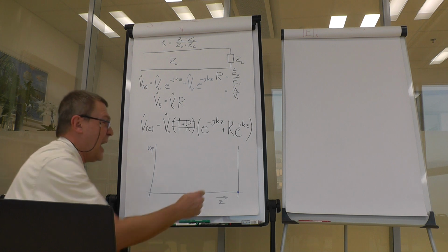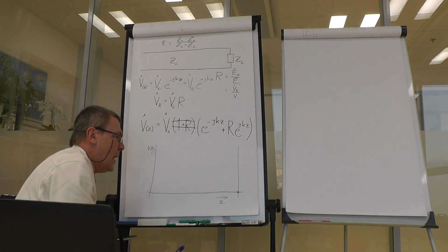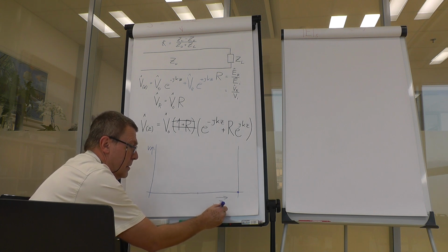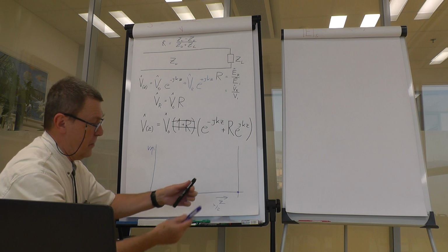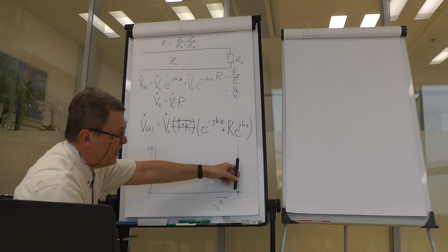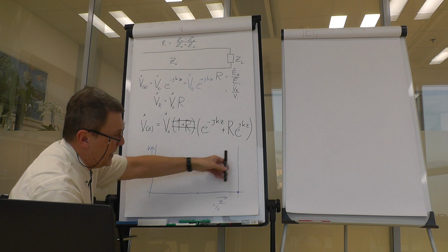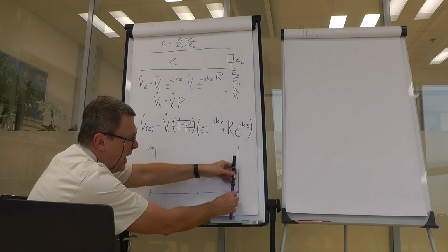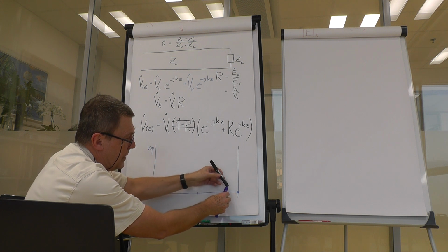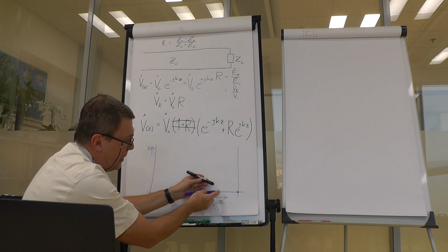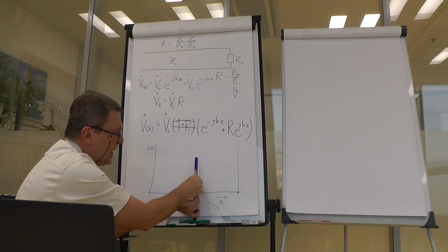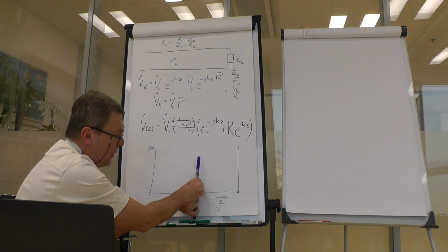So it happens that after just 1/2 of a wavelength, we have one voltage with this direction, the incoming wave, we have the other voltage, the reflected wave, and now those two waves, as the phase along the way changes, finally stand again in antiphase, just 1/2 wavelength from the original short.